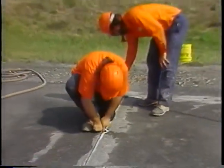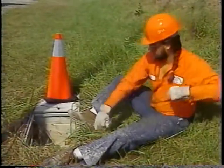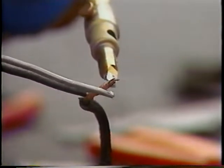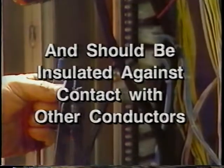Now that these sensing element cables have been installed and tested, they need to be spliced with the lead-in cables to the controller cabinet. All connections should be soldered, insulated, and sealed in a waterproof manner. Also, microloop detectors perform best when the cable shield is not terminated at both ends and is insulated against contact with other conductors.